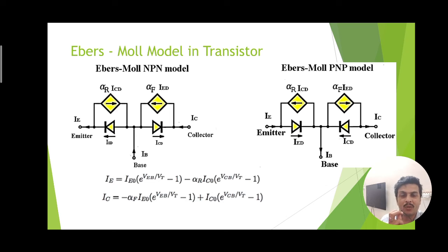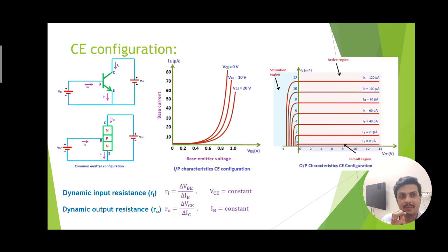Depending on which diode is switched on, we can keep the diode as a short circuit, and if the diode is off, we can replace it by an open circuit, and thereby explain the circuit operation using circuit theory formulas. Therefore the Ebers-Moll model helps us find the solution for the transistor if we want to build the equations in terms of a circuit theory model.